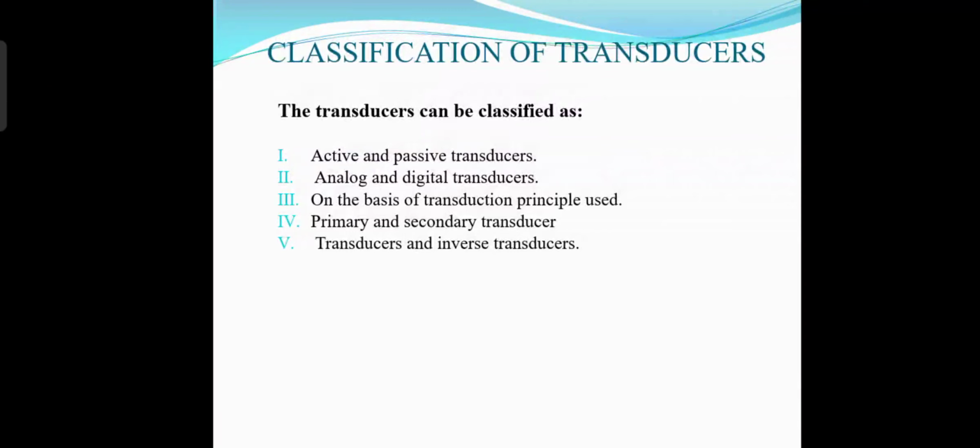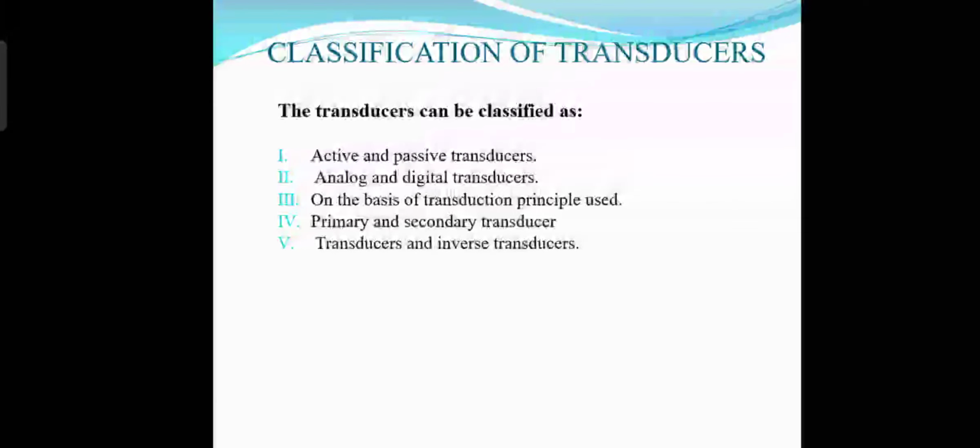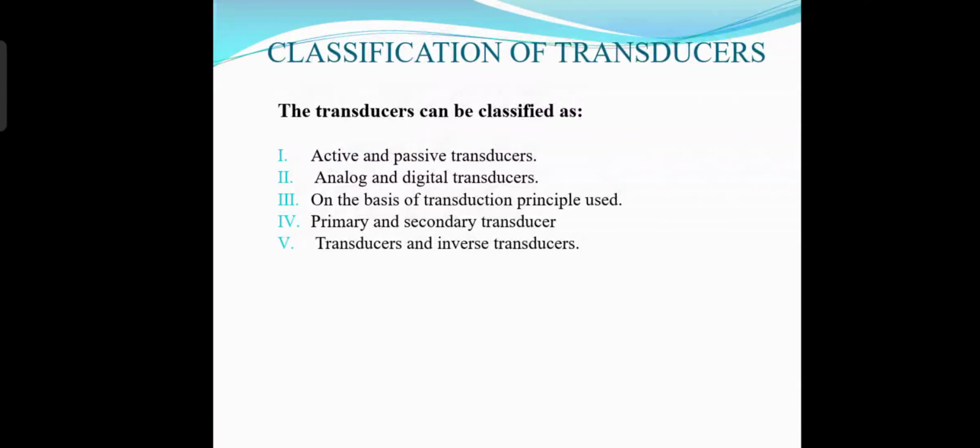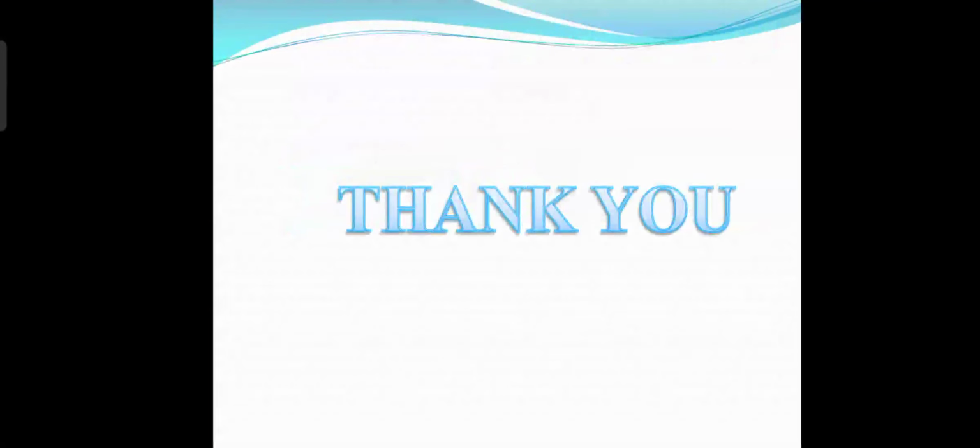The output of the digital transducer, being binary in nature, can be easily represented either by opaque and transparent areas on a glass scale or by non-conducting and conducting areas on a metal scale. Glass scales can be read optically by means of a light source, an optical system, and photocells. The metal scales are scanned by brushes making electrical contact with the individual tracks.